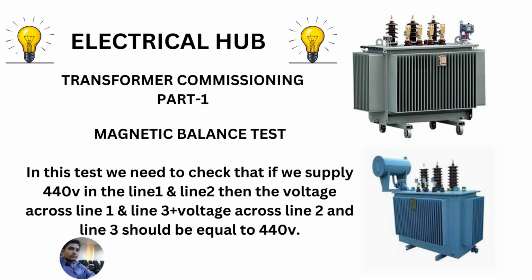So here we need to supply 440 volt in two lines, and we can check one line with respect to the line which is not used. And if the summation is equal to 440 volt, then it is good. If not, then it's a matter of concern.